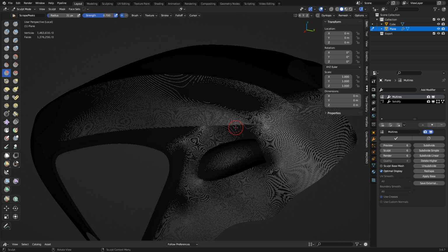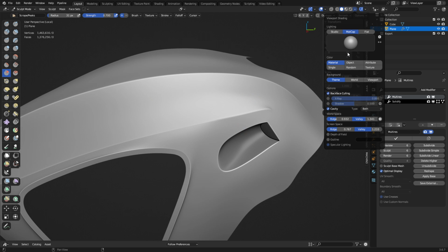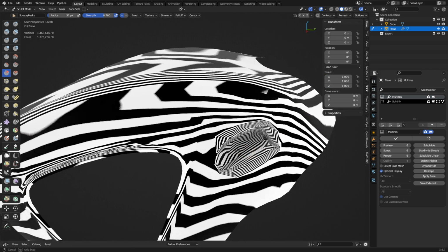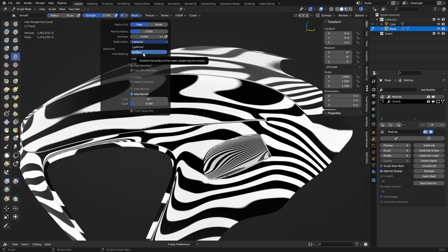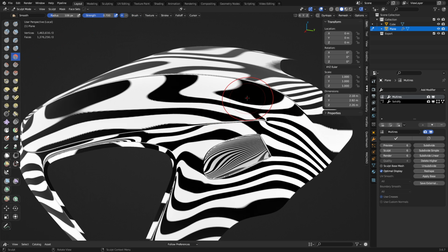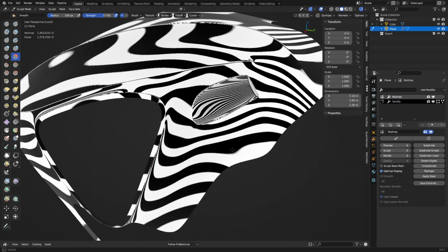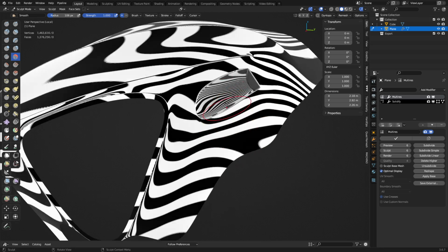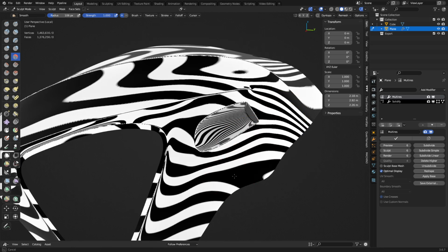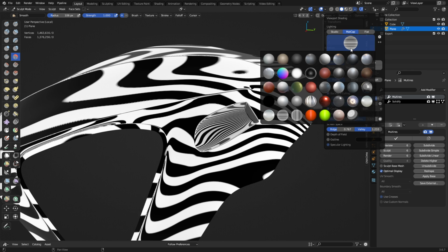So if we wanted to do some surfacing, this is when you get those zebra stripes going. You can use the smooth tool, and you can set it to surface. And you could try to work out little minor errors perhaps if you needed to on the surface here. Sometimes you've got to crank the strength and click a lot. But eventually you'll start correcting it little by little, which is kind of interesting. Possibly. Now, you could also do it at a lower resolution. It'll take effect faster.